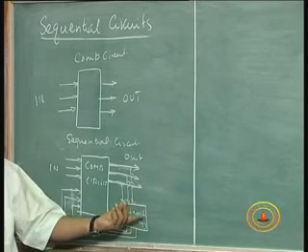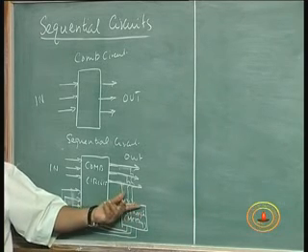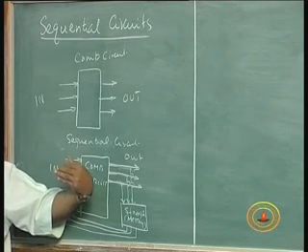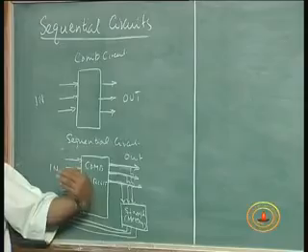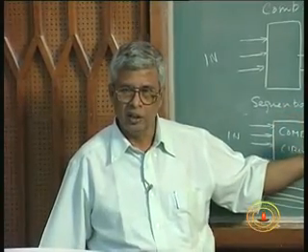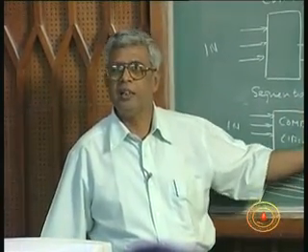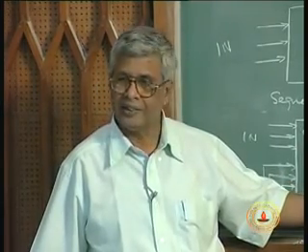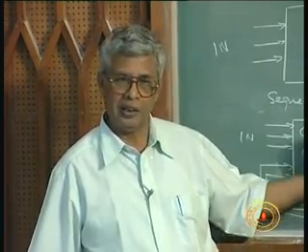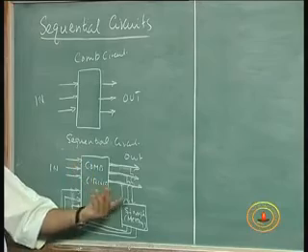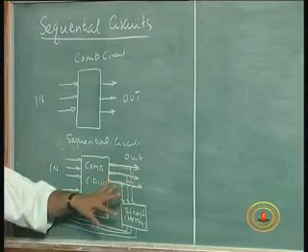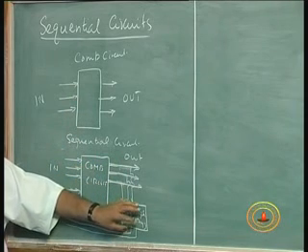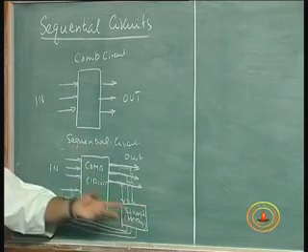But in between we need to have these elements for storage. This is what is new, the feedback component, the feedback concept, so that the circuit will remember this behavior. That part is the only new thing here. Once we know how to implement this, we can build this combinational sequential circuit using this sort of model. We have already done the rest, so this extra thing is all we need to do in order to realize a sequential circuit.